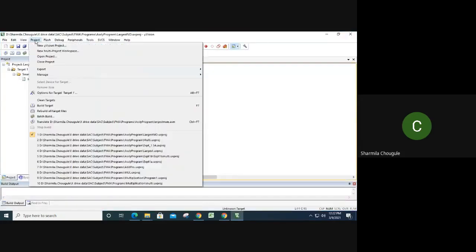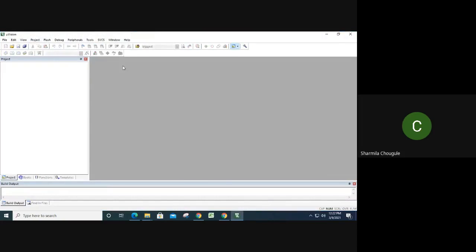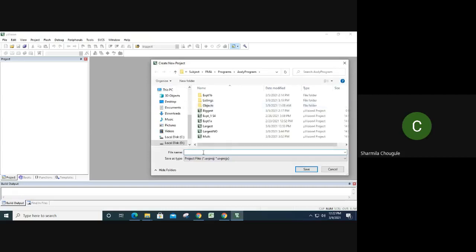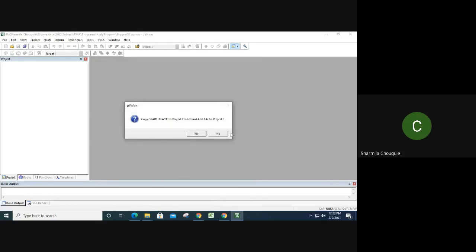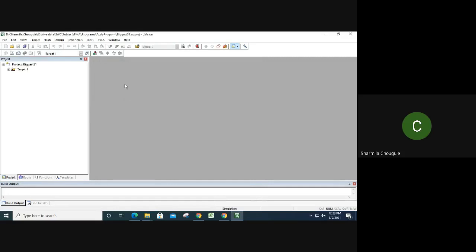Okay, so I'll just open the Keil software. I'll close the project. Okay, so I'll open the new project, new MicroVision project. I'll write the name as biggest, your batch is S1. So biggest number for S1 batch. Okay, save. Then it will ask for the device. Okay, so it is 89C51. I'll select this 89C51. Then you have to select no. So your target has been added to the project group.